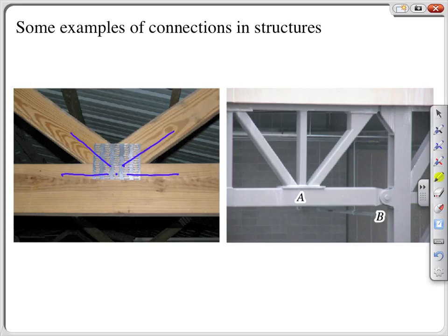By the same token, over here on this bridge truss, right here at A, I'll draw a dot, and this will be one joint here. I'll make this a bigger dot to emphasize the pin connection here. We obviously have a pin connection here, but we would approximate these things this way, even though the actual connection between those members is more rigid than a pin. We're going to treat them as a pin anyway.